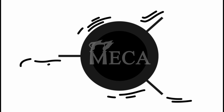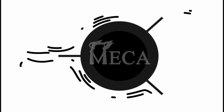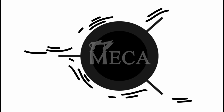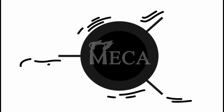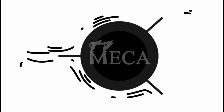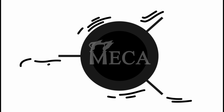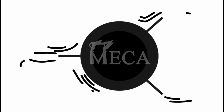Helical strakes are one of the most common solutions to address structure vibrations. They consist of thin fins that wrap around the stack in a circular shape. These fins cut through the wind, disrupting possible vortex shedding. Using strakes does have some disadvantages and limitations, so please refer to articles on our website for more discussion